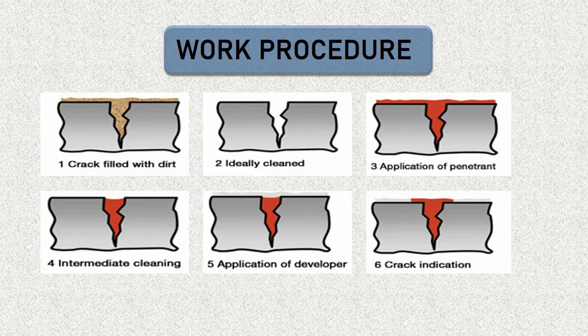Then, the inspection. The inspector will use visible light with adequate intensity for visible dye penetrant. Ultraviolet (UV-A) radiation of adequate intensity, in microwatts per centimeter square, is common, along with low ambient light levels. For fluorescent penetrant examination, inspection of the test surface should take place after a 10 to 30 minute development time, depending on the product kind. The test surface is often cleaned after inspection and recording of defects, especially if a post-inspection coating process is scheduled.